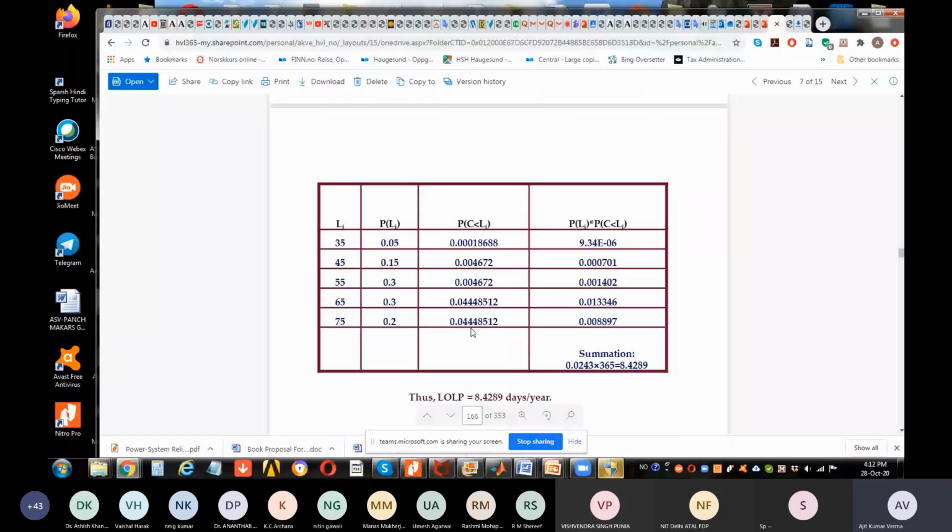So this is it. This could be the load profile, and any of these could occur, and of course the capacities can lead to loss of load. So these are the LOLP corresponding to these peak loads. If any of these states can occur, then this would be cumulative.